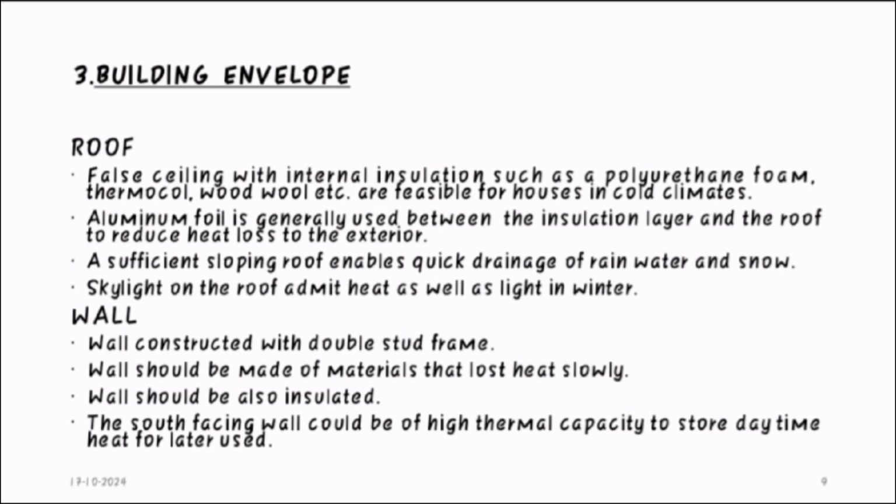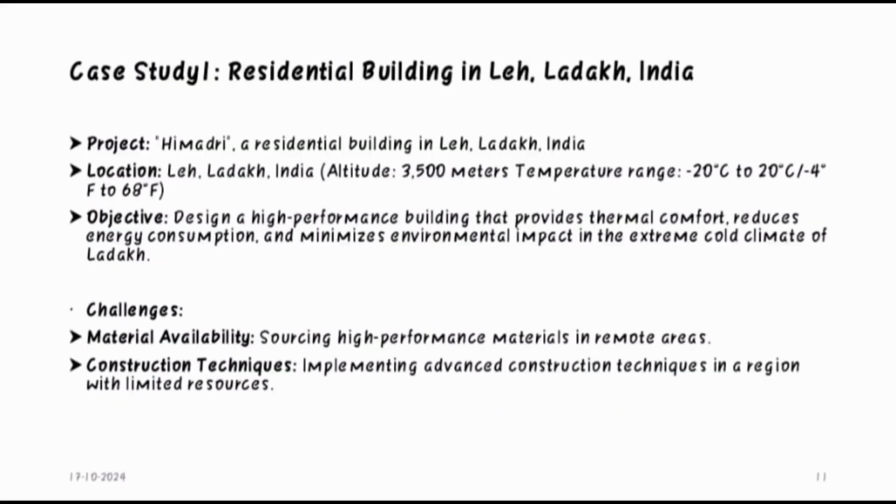Next is wall. Wall constructed with double stud frame and should be made of material that loses heat slowly and should be also insulated. The south facing wall could be of high thermal capacity to store daytime heat for later use. Move to next slide. Moving on to case study.